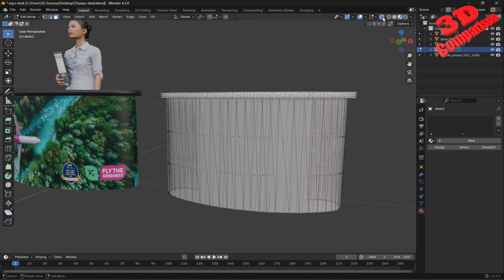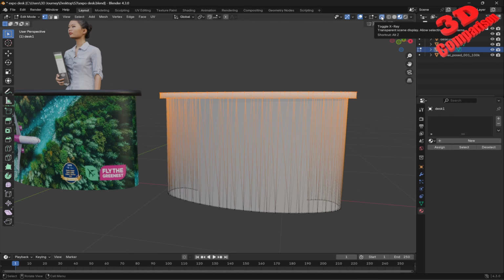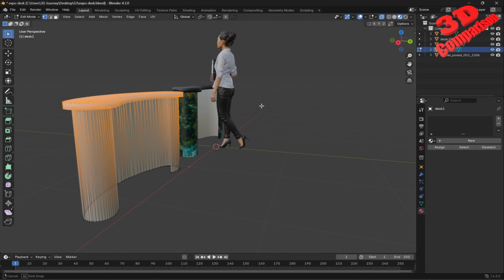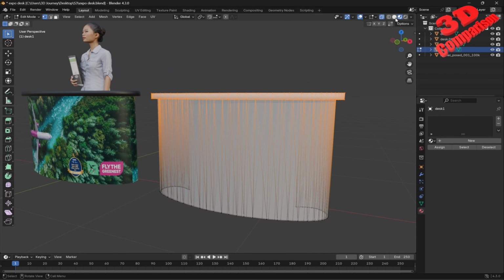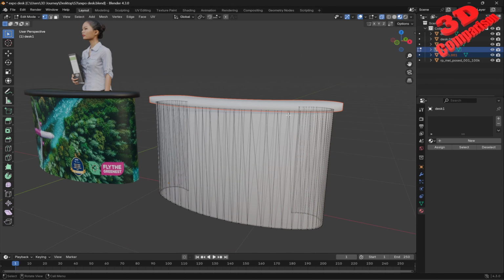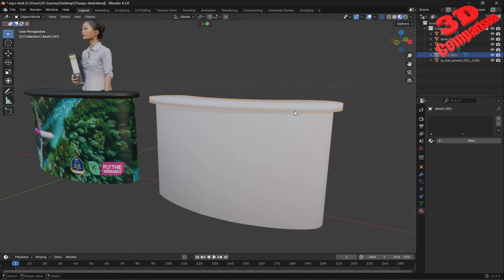So we can do something different. I can go within selection vertex. I also enabled X-ray, so this will also select the vertices that are not visible to the camera. And with this selected, I can press P and I will do a separate selection.